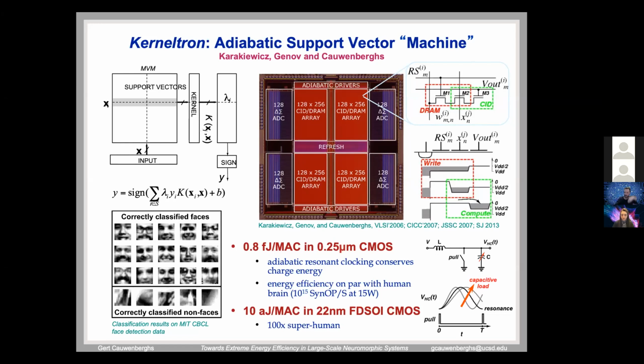So there's the hot clock, and we only flip a switch when the voltage crosses 0. That's the key, the mantra if you want for adiabatic computing. You can only open or close a switch when the voltage crosses 0 on this hot clock. If you do that consistently, you never waste any energy, because every switch has either 0 current or 0 voltage, so you never have any power dissipation. That's the way you can really operate at zilch.